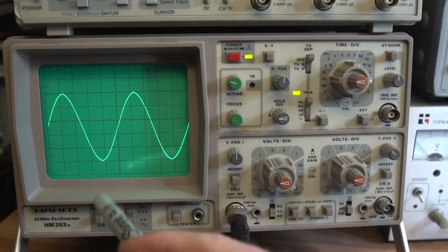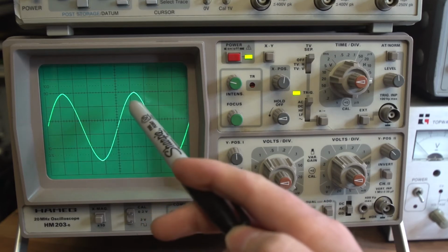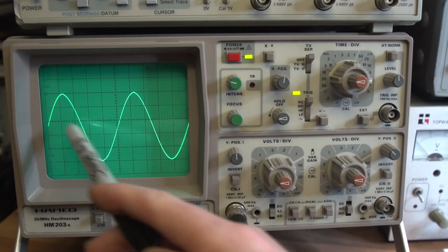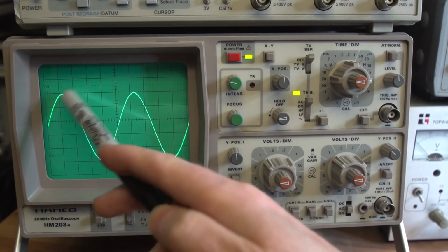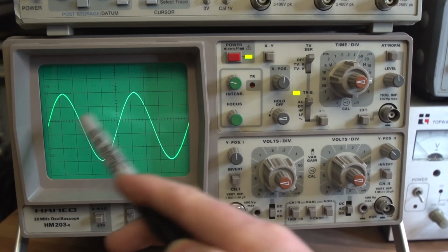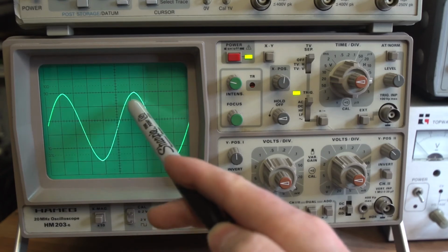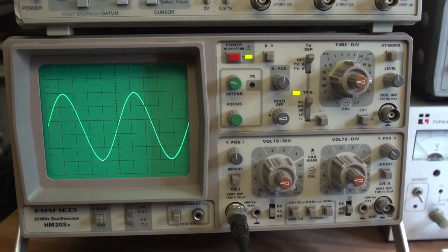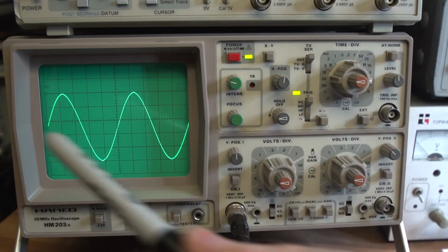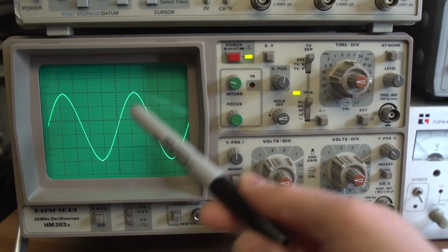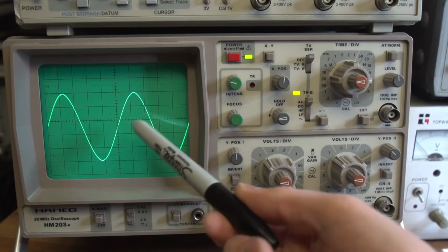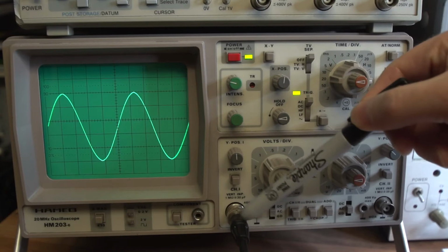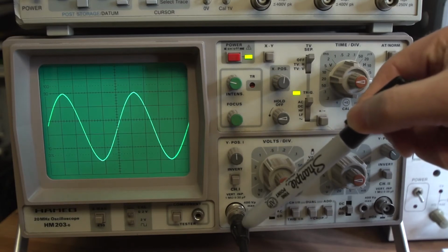So the scope's told us 2 things straight away. It's told us the amplitude of the signal, how big it is in terms of voltage, and it's also told us the time period it's taking for a complete waveform, where the waveform starts to repeat itself. That's one full cycle. These are cycles. What if you want to know what frequency that is? We know what the time is, but what's that in terms of hertz or kilohertz or even megahertz? What frequency is it? Well, you could just take the probe and plug it into a frequency counter and it would tell you straight away.